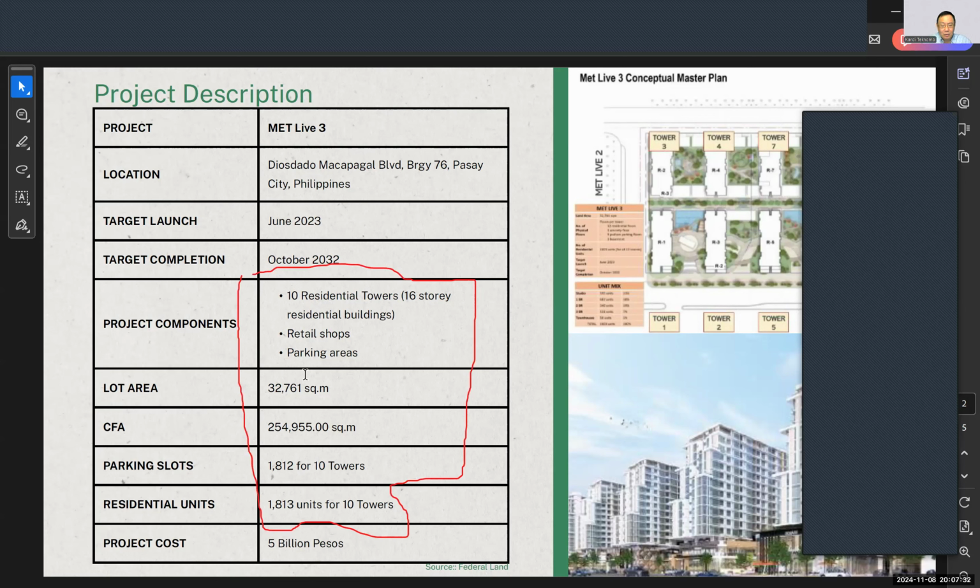You just find the literature, what is the trip rate for this, and because you have the square area and so on, you will know how much traffic will be generated from here and attracted to this also, because you have a retail shop. You need to know the area of the retail shop and the parking area, or parking area you already have, right? So from there, you can calculate the trip attraction and trip production.